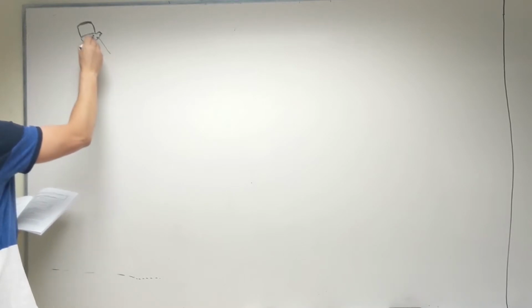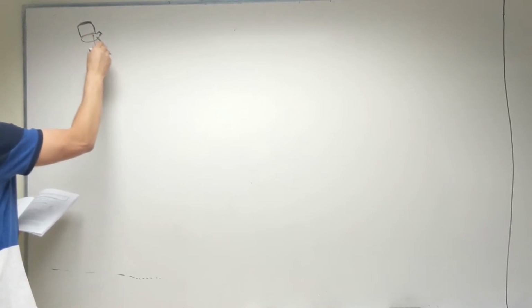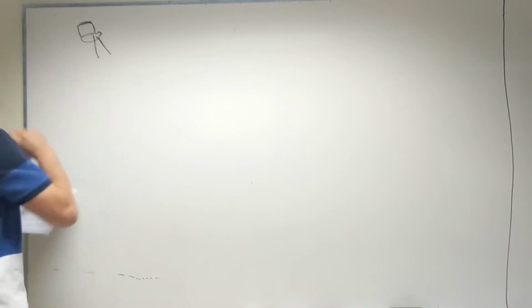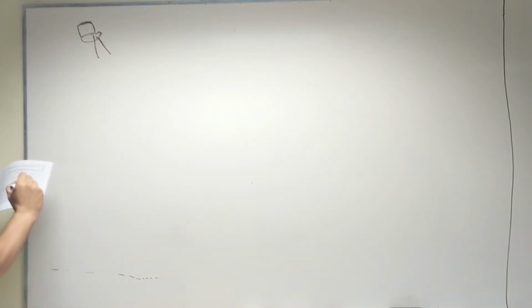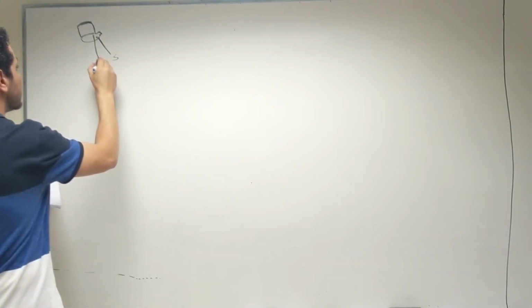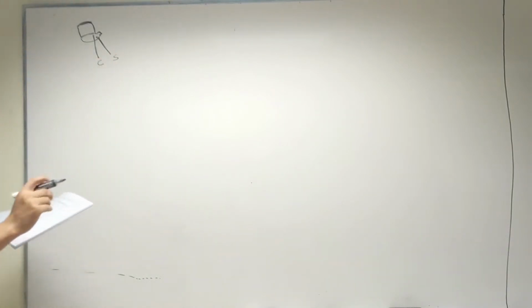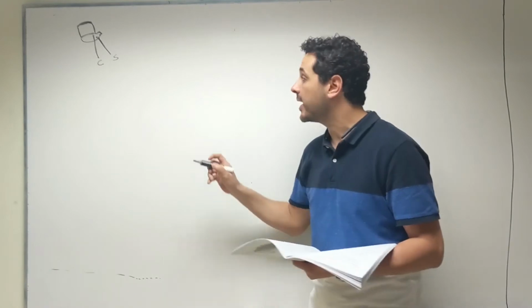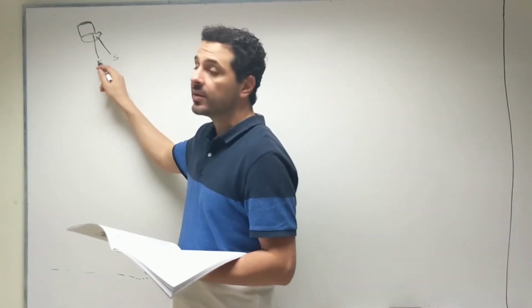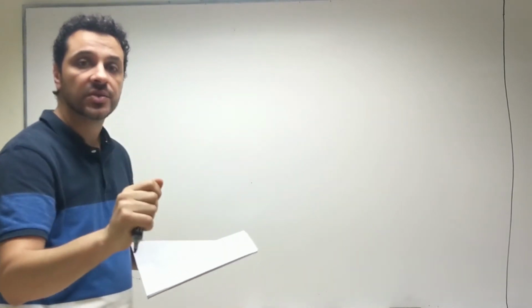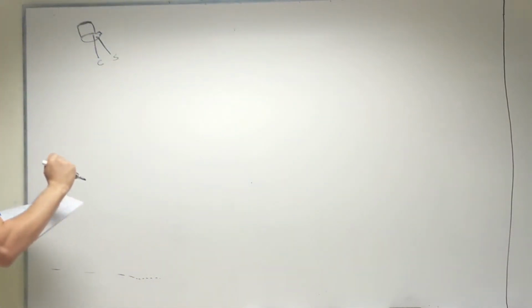The 2 terminals around the edge, at the left and the right of the metal edge, are the source and the body of the transistor. So the source and the substrate, or the body of the transistor. The body has no use at all in our experiment. That's why it is usually connected to the source. Usually the body and the source are connected together for the whole experiment.